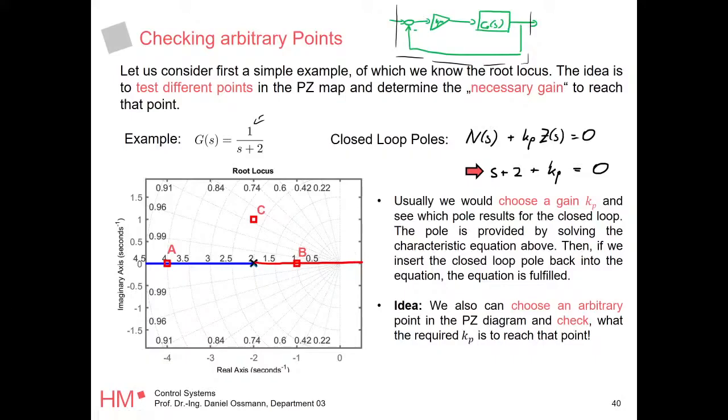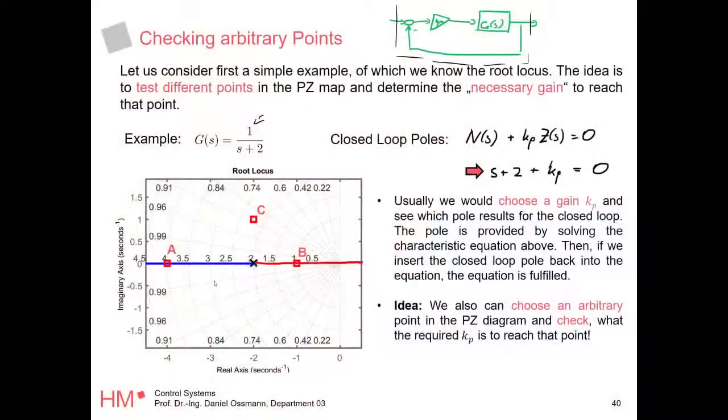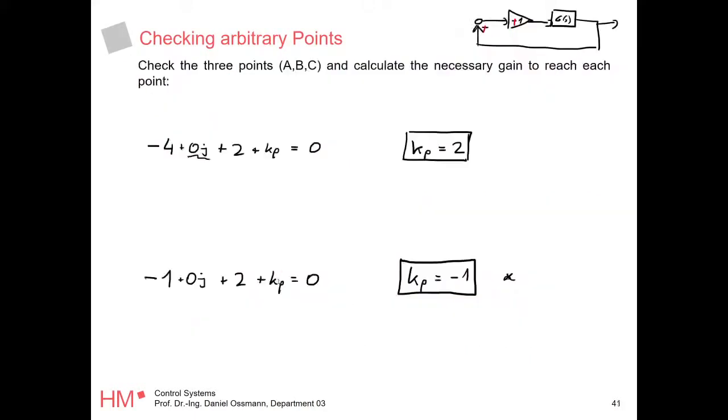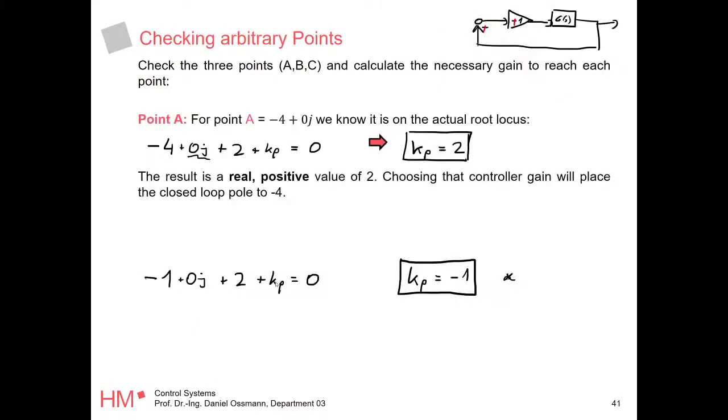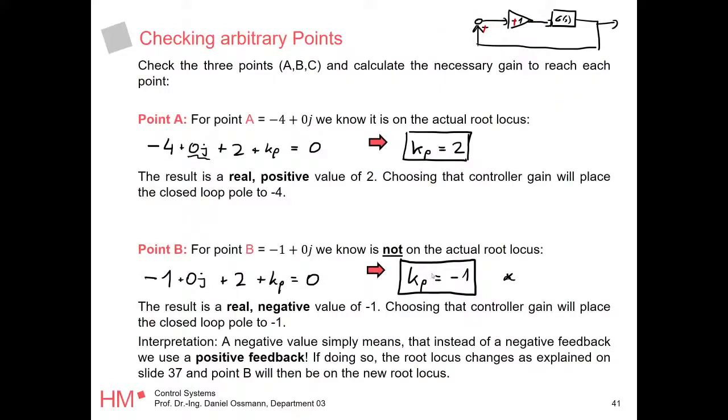And I always told you, usually positive feedback is not a good idea, except when it comes from the coordinate system, like flight mechanics. But usually, it's not a good idea. And this is what you see here. So if you want to make your system worse and make it slower, you basically need to have positive feedback. You want to destabilize your system. This is the outcome here. Okay, but still, we could design a controller by just changing the gain, right, for that point.